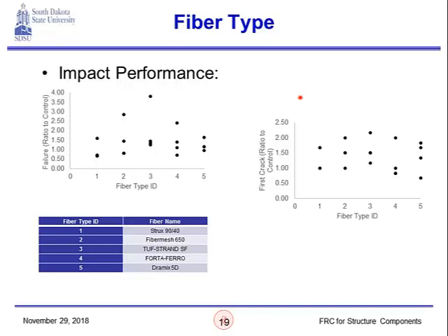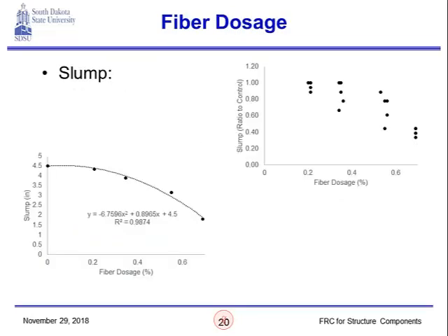So a different kind of test, more sophisticated tests, would be more beneficial in this case. Something like a compressive or tensile strength test where we have variable strain rates applied and that is more quantitative in nature would be a better test for impact. But for our case, we couldn't really draw any conclusions here.